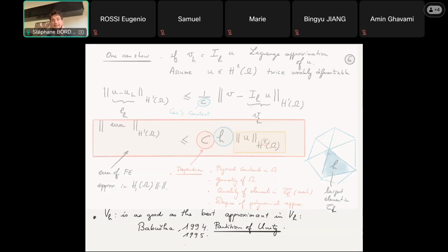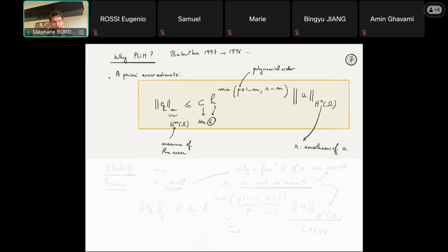And so I'm dealing with all these cases. And what I want is to know, let's say I use a finite element method with linear polynomials or quadratic, cubic, whatever. I'm using that. So that is what is written here. The P, that's the polynomial order. For now, forget the rest of the equation. We'll come back to that slowly. So we have that. That's the polynomial order. And let's say that the mesh size is H. That means that the largest element in the mesh is of size H. If it's a regular mesh, it's just the size of the element.